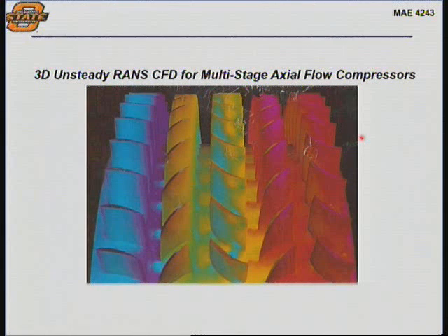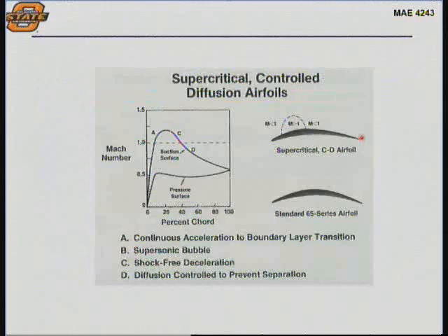And so now you can start to look at really how the flow is moving, and it has an even bigger impact in turbines, as we'll talk about later, regarding where you put cooling flow in. Once you know where these secondary flows are going through the turbomachinery passages, the better you can cool the turbine blade.